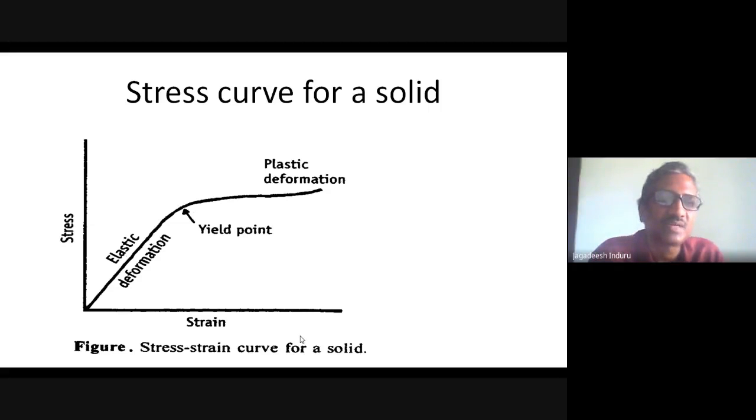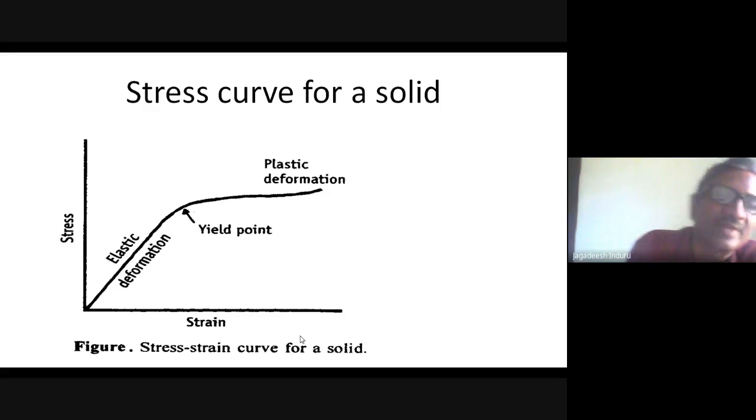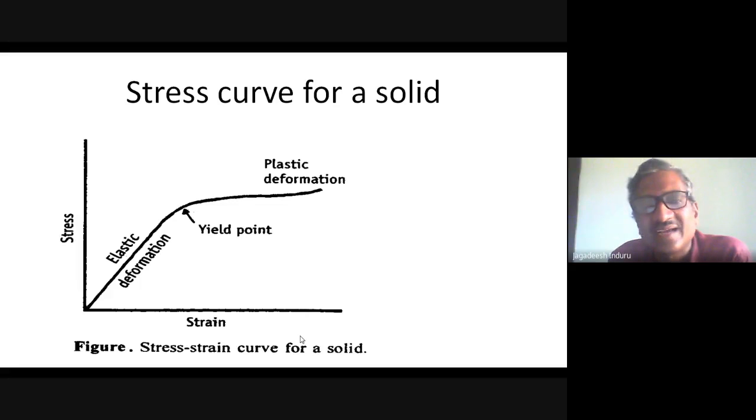Now, if you want to convert such powder into a tablet, you need to apply the force, that is a strain, beyond your yield point. In that case the material will behave as a plastic in nature and it will break. It means you are creating a flaw, a crack, and it becomes broken, and it behaves as a plastic only after the yield point. Wherever the yield point is higher and higher, tablet manufacture becomes tougher and tougher.